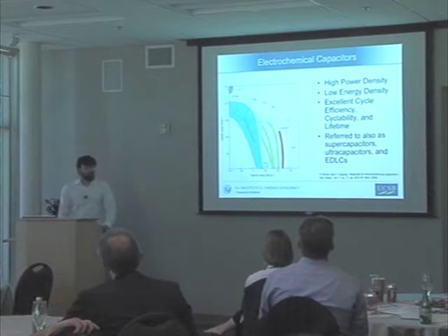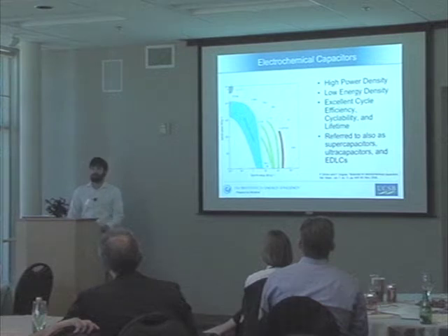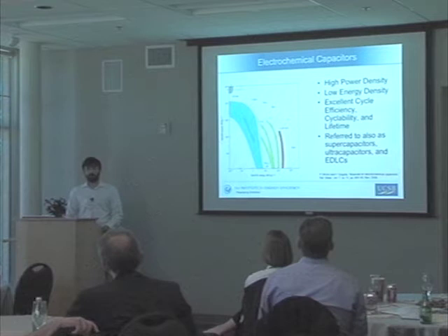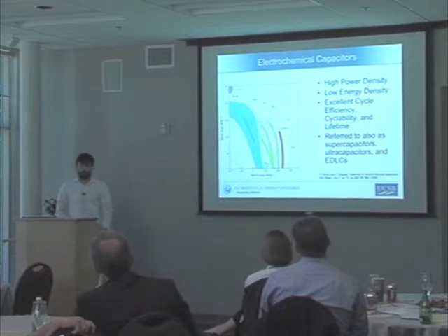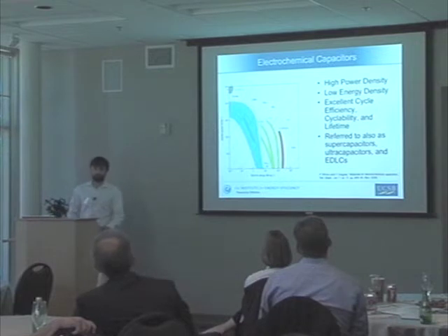The problem is that this is a large amount of energy over a very short interval of time, which is a high power, and lithium-ion batteries cannot absorb such high power. You'll damage the lithium-ion battery pack. So you need something to go in tandem with this. A good candidate is electrochemical capacitors, because although they hold much less energy per unit weight, they can absorb energy and deliver it very, very quickly, up to an order of magnitude more quickly.